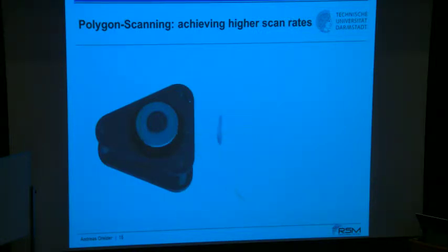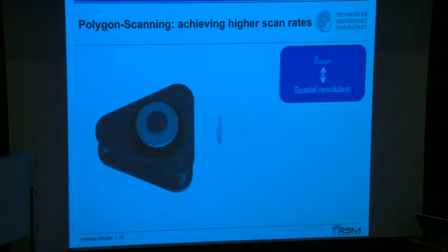And the benefit of this device, still being mechanical, is that you can now increase the scanning rate up to 10 kilohertz. That was something of the limit we could achieve. And already this is getting a bit frightening, because now you have a device in your lab, a polygon of this size, turning very fast, and that needs to be controlled to be, ideally, free of any jitter. So this is a control problem, because every time you have your swept planes, you would like to have them at the next sweep, ideally at the identical position again. And that is, of course, difficult.